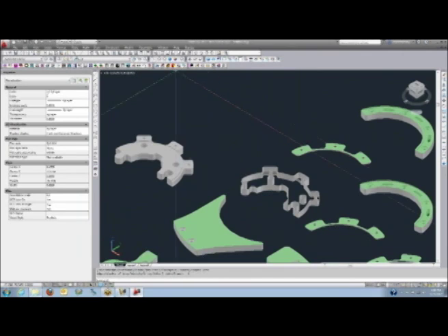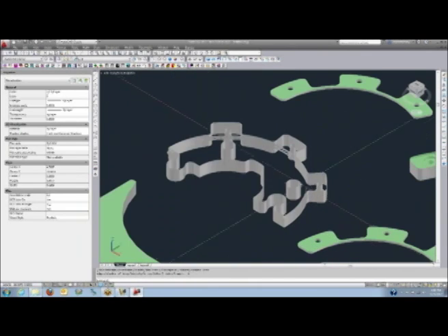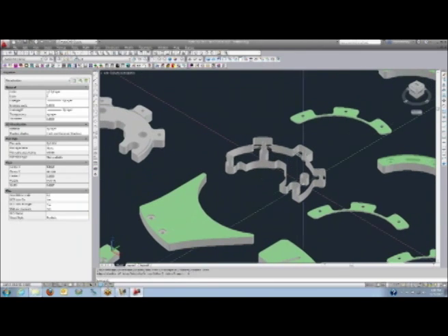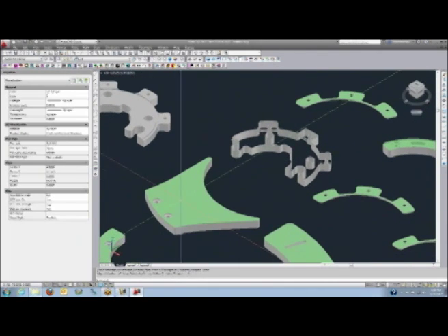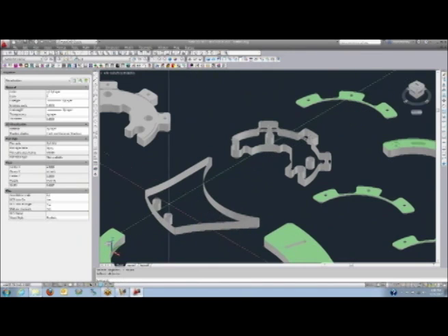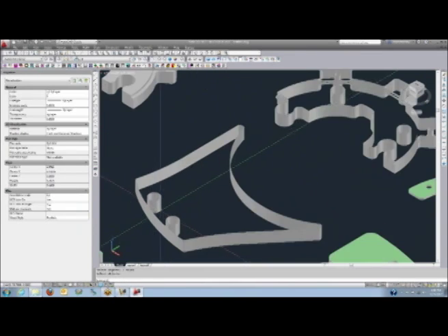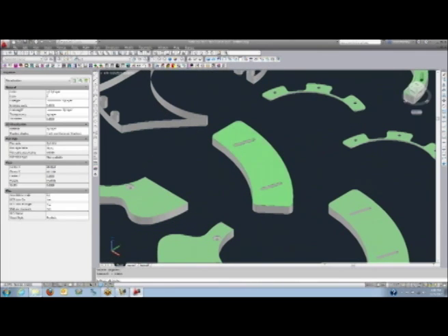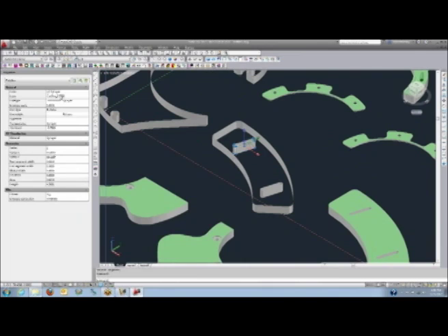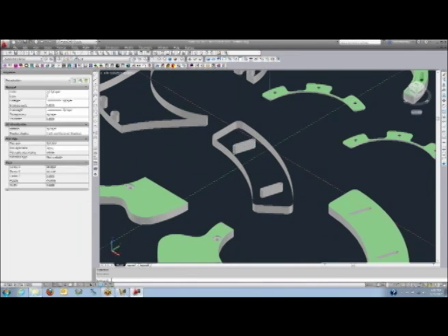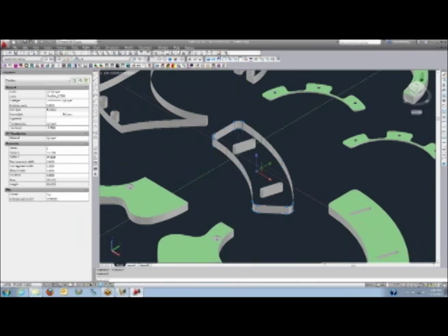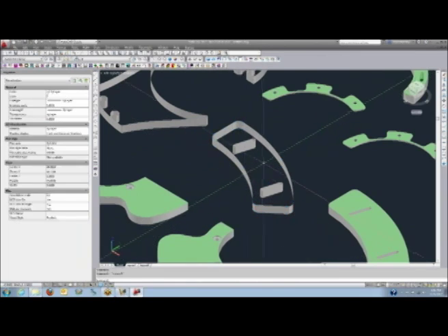Okay, so in a shaded mode, you can see the solid, and you can see the geometry that was created from that solid. In all cases, it's the same. There are the features that were recognized from that solid. Features are geometry on different layers. Any CAM system can now cut that geometry on different layers, and they also have a thickness built in as well, so that the CAM toolpath generator will generate the toolpath based on the thickness of the geometry.